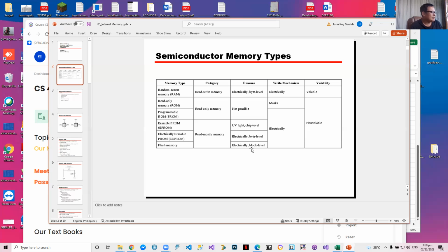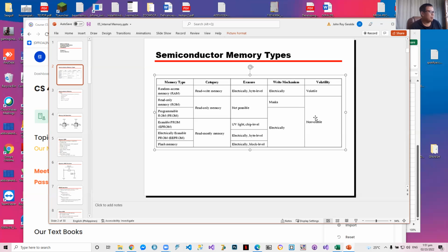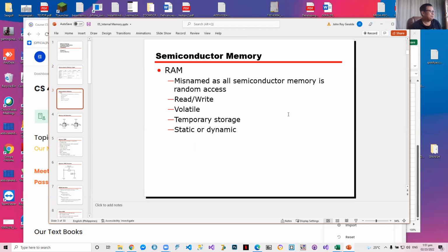Okay. Now, flash memory and electrically erasable ROM are done electrically and can now be done by ordinary computers, no? The write mechanism is electrical. This is masking, no? This is a process using an EEPROM programmer. Okay, a programmable ROM programmer. It's a circuit where you place the ROM and then save the value there, no? Sequentially, no? So ROMs are non-volatile, which means that even without electrical power, they will store their memory.